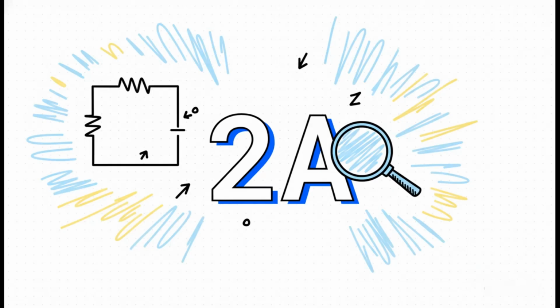So to get that number, we can use the current divider rule. We figure out how the total current from the 12-volt source splits between the different paths. And when you do the math, it turns out the current going through our short circuit is exactly 2 amps. And just like that, that's our Norton current, IN. First piece of our puzzle is solved.